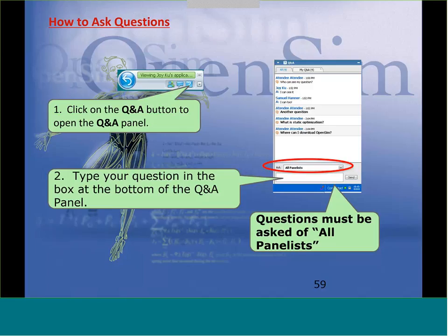Yeah, so in that last part of Daisy, I did look at the patellofemoral contact stresses, and generally the contact stress increased for the lunge activity, which carried more load, and also the location of it increased as a function of flexion. But generally, their location and position was activity independent.